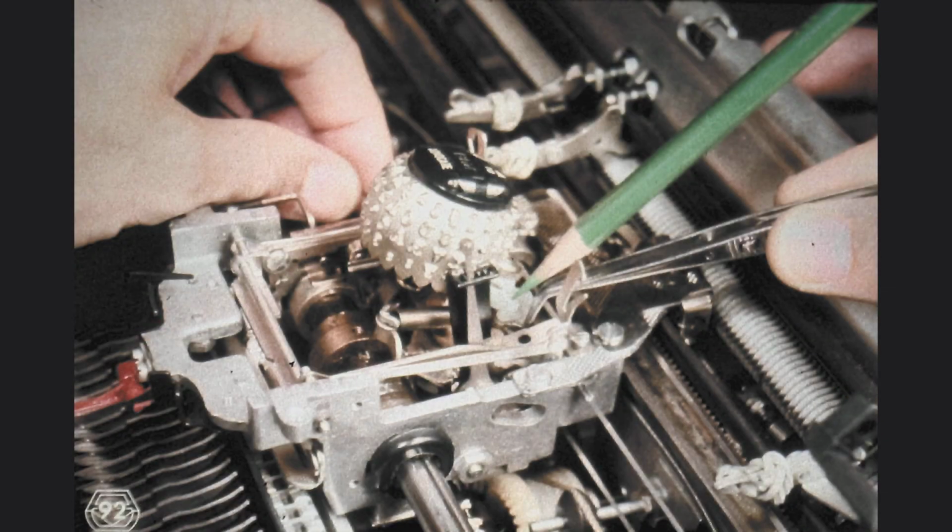The other end of the tilt tape is connected to the tilt pulley sector mounted on the rocker. After you have thoroughly inspected the way the tilt tape is threaded, particularly under the escapement plate or bracket, go ahead and remove the tilt tape from the machine.